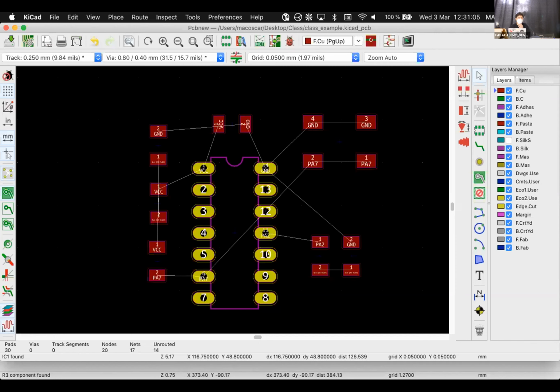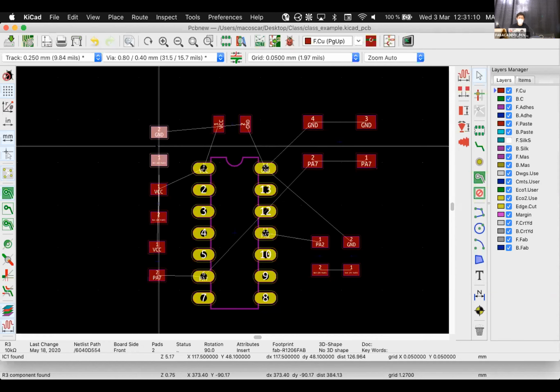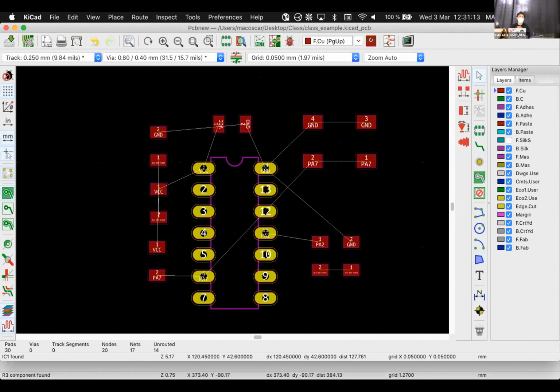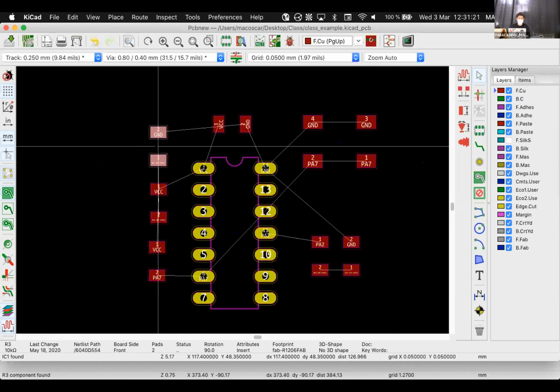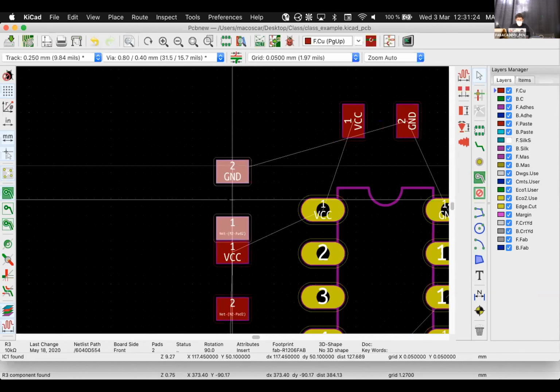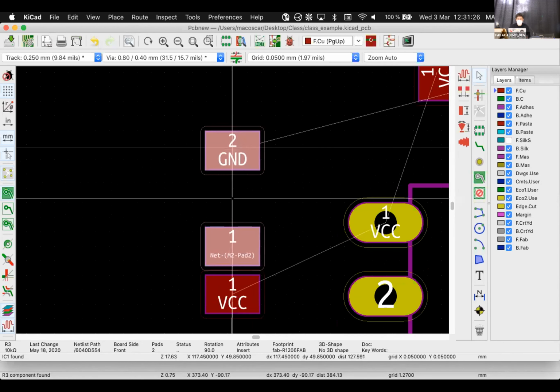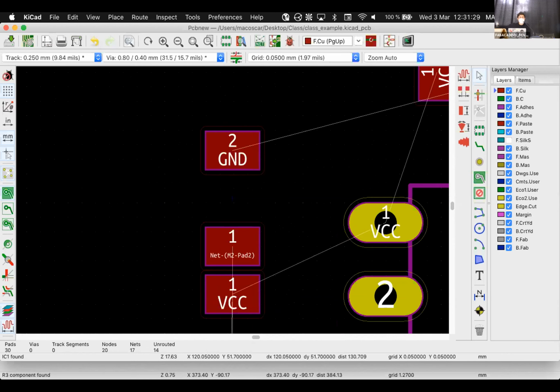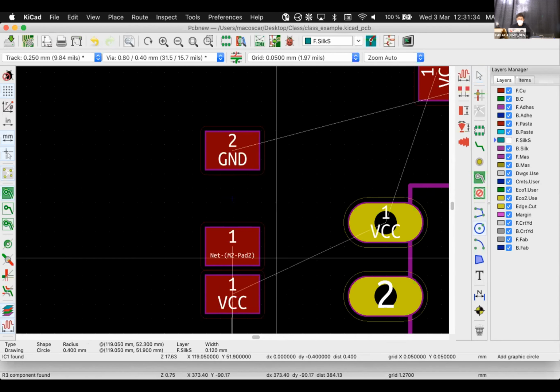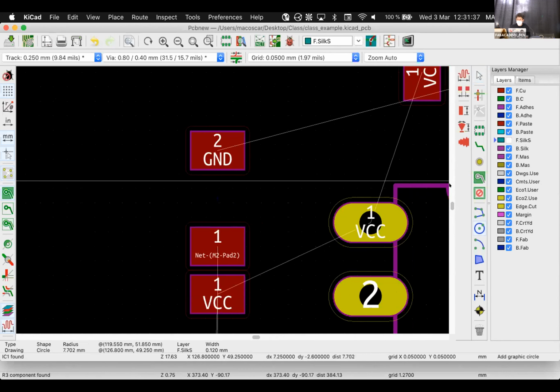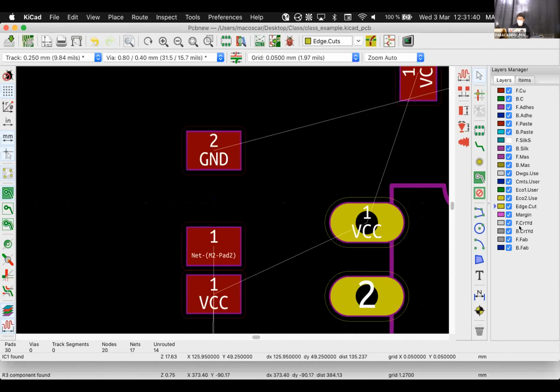Is that clear? What I'm trying to say is that the manufacturing process puts a limitation on how close things can be to one another, because the end mill is not able to go through otherwise. Imagine that I put this here, super close, and I'm asking the end mill on the machine to go between them.